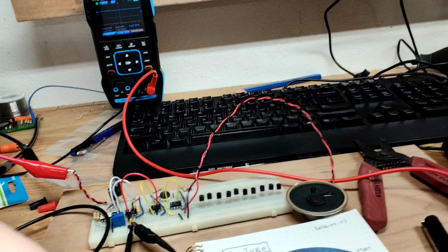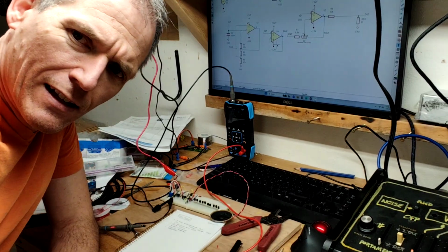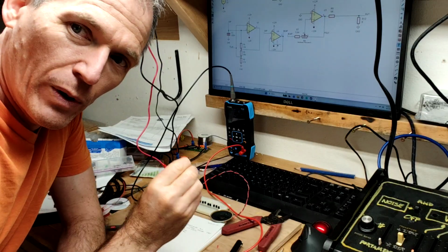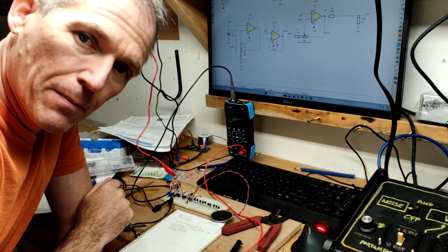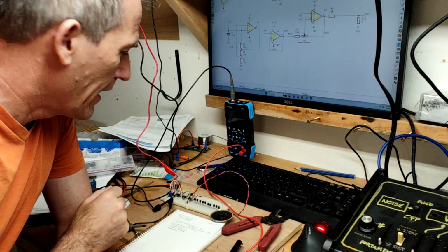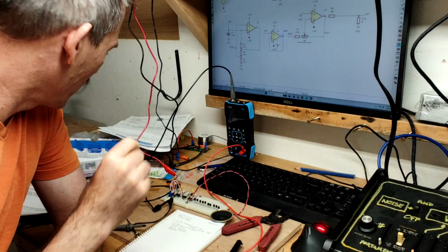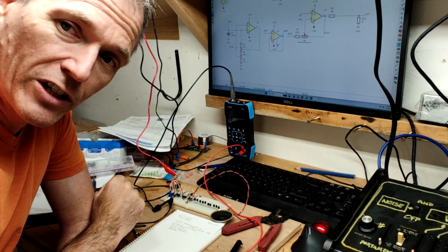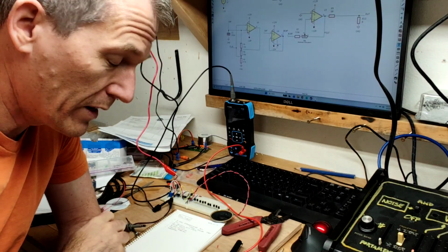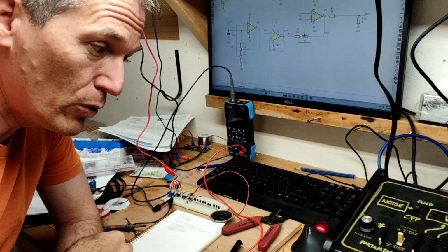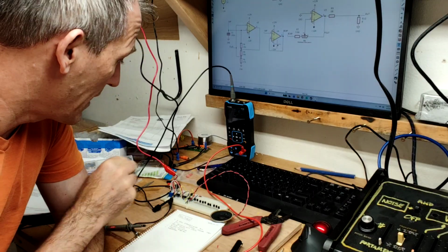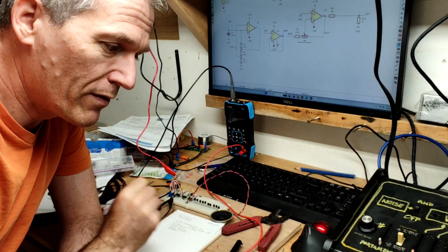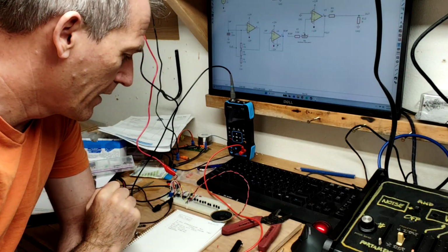And now, I really like the sound that has. It's a pretty cool type of saturation. And so I want to find a way to capture that overdriven LM741 sound. And one nice thing about the LM741 is that it can drive to short circuit indefinitely. So it has some protection in there that it's going to be okay. One thing it doesn't have, though, is heat shutoff. And so I do have to be a little bit careful about how much power is being dissipated by that LM741, but we can definitely get it to a state where it's overdriving in order to produce that kind of interesting saturation.